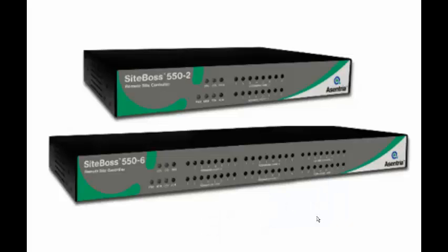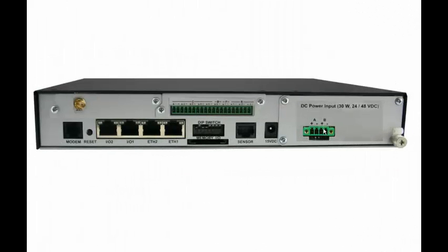The base I/O built into the 550-2 unit starts with 2 serial RS-232 ports, I/O1 and I/O2. I/O2 doubles as a console port for talking to the 550's command line interface. The 550 also has 2 built-in Ethernet ports. Ethernet 1 is the primary port, typically used for connectivity, and Ethernet 2 can be used for a local LAN, port forwarding pass-through, or other applications.